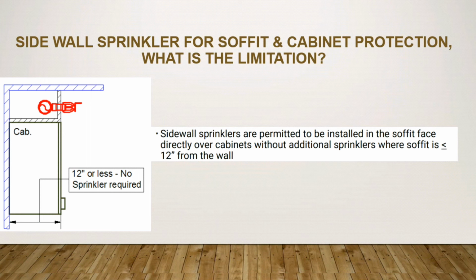And the next question is sidewall sprinkler for soffit and cabinet protection. Here both the soffit and cabinet together. So what is the rule? Sidewall sprinklers are permitted to be installed in the soffit space directly over the cabinet.